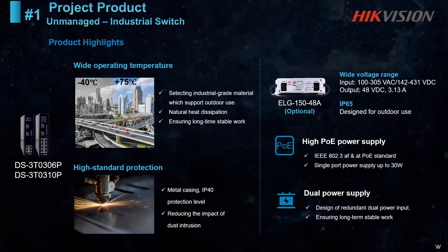And these switches also contain high PoE power supply. So if you have PTZ cameras that require higher PoE power, you can plug those PTZ cameras into these switches as well. And Varuna, I think this kind of power supply is more critical when we go into industrial environments, because the voltage is not very stable in industrial environments, right?